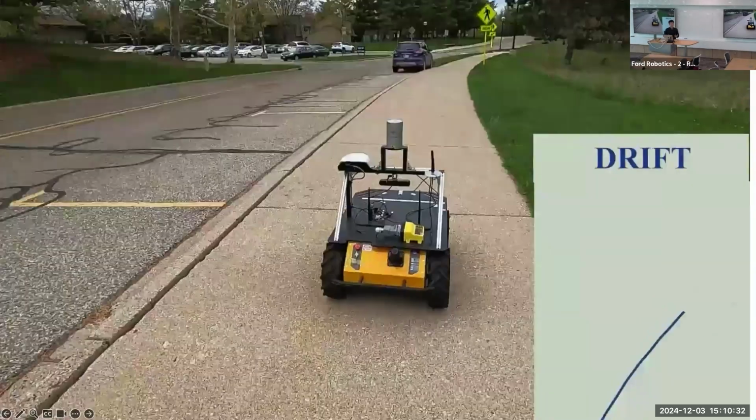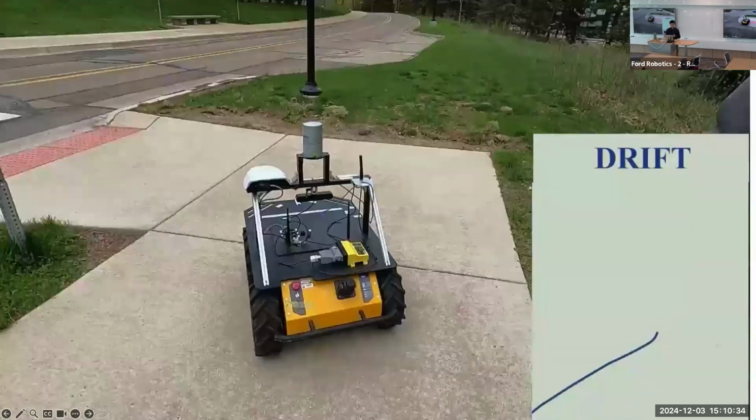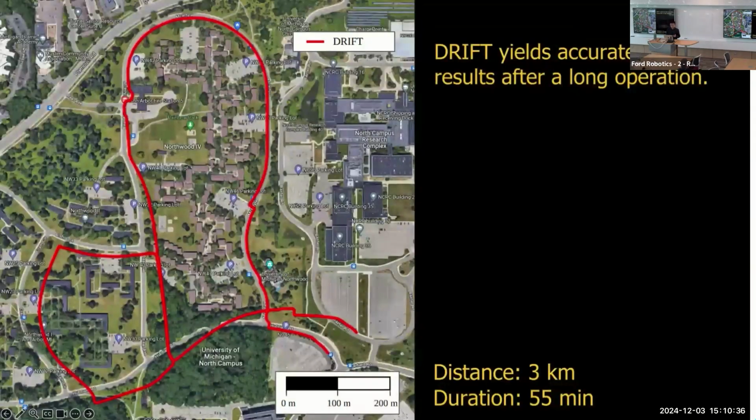In order to test the limit of DRIFT, we drove these Husky robots on campus for about an hour, and wanted to see how far we can push this algorithm without using vision sensors. And qualitatively, it's like this. For about 3 kilometers, there's only 100 meters of drift. This is great because it means that even though our vision sensor is blocked, we can still track the robot for an hour without the robot being lost.